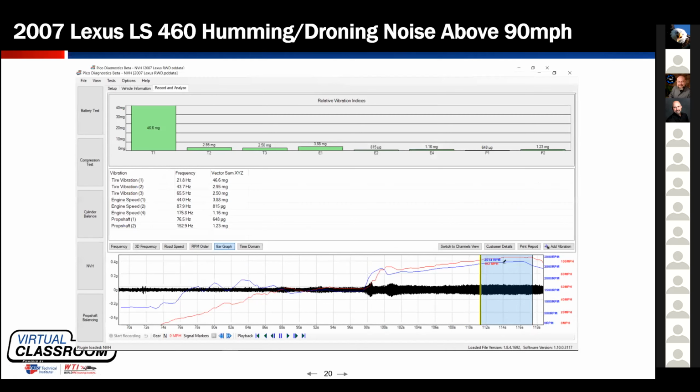The trick is, okay, you measured it, you can hear it. Do you see where it's happening? Well, Adam, right here, your humming noise is happening in a tire-oriented order one. Remember, the one is how many shakes per revolution. So if I said it has a tire one order vibration, that means every single rotation of the tire, it produced one shake every revolution. If I said it had a T2 vibration, it would be producing 2 shakes every revolution, a 3, a 4,